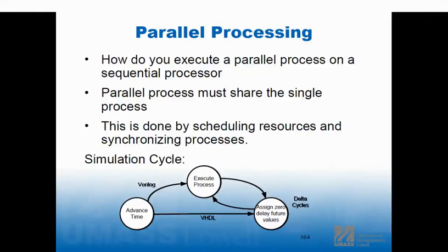The way you can tell is you run your simulation and it goes dead. You hear the fan turn on the laptop, like, this thing is really trying, but I'm not seeing it advance. The simulation time isn't changing. And then all of a sudden you get an error on the simulator that says delta time exceeded. For whatever reason, the delta time in ModelSim is this gigantic number, like 30,000 or something like that. It takes some time to do it. I've done it.